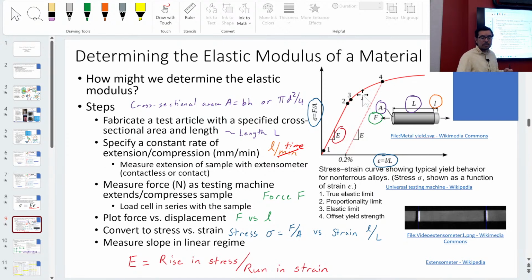If you go past this point of no return, then you come back down with the same slope, and we'll talk about slope in a second. You come back down with the same slope, but this thing had already banked over, so you can't come back down to the same spot. You're always coming back down to the same slope, but where you start your return matters. So if I start my return on that initial elastic line, I come back down to where I started. But if I get over the bend, then it will be permanently deformed.